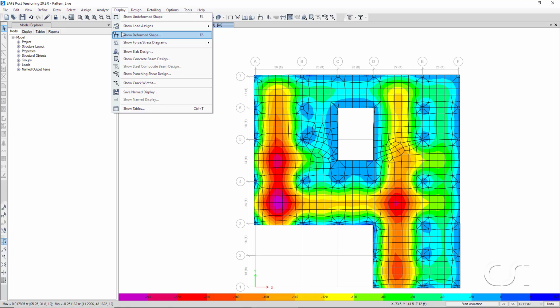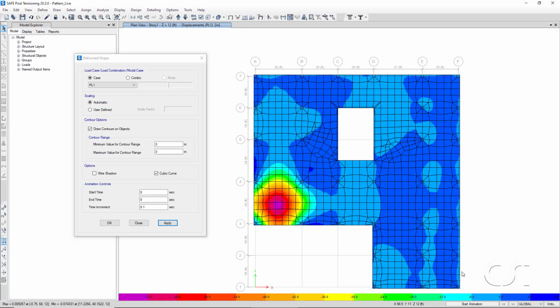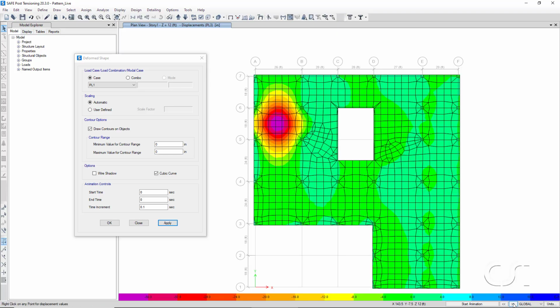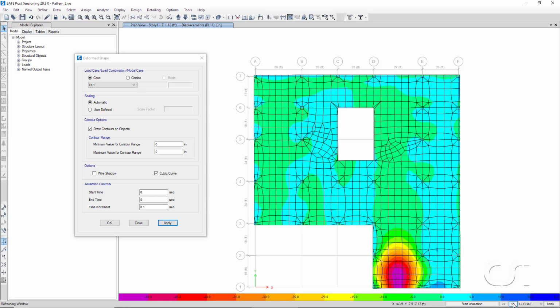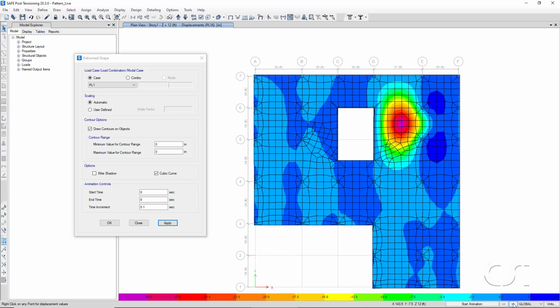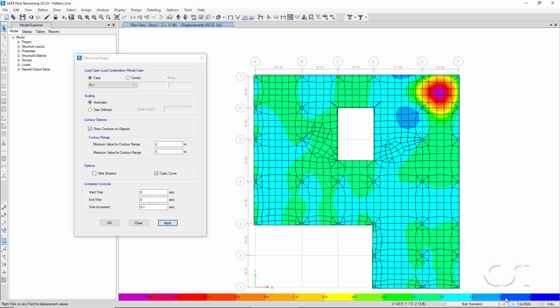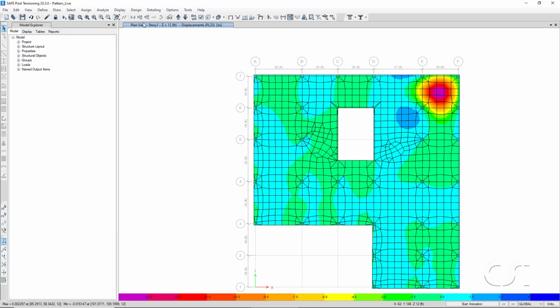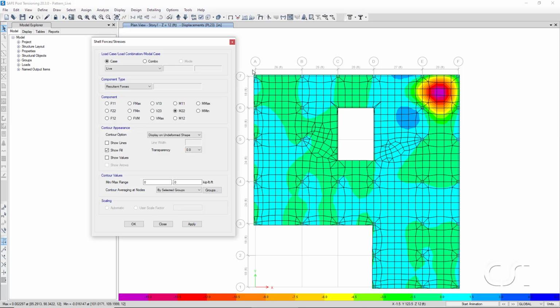This time, when we step through, the analysis results are displayed for each of 23 load cases, rather than for the steps as determined by the slab panels of a single load case. And the moments are displayed using the range add combination case rather than a single load case.